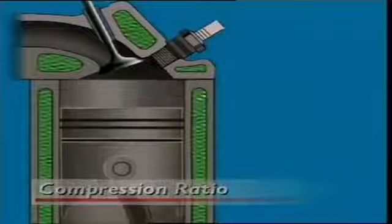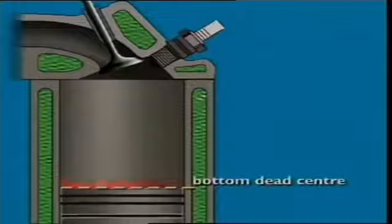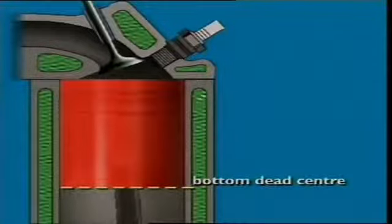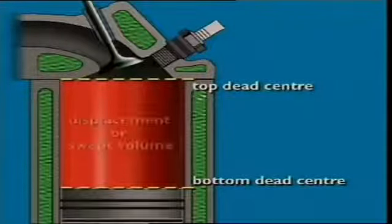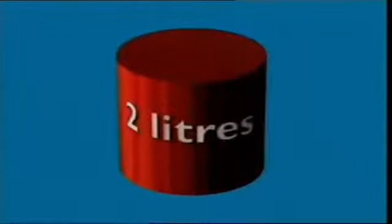Displacement is the volume a piston displaces in the cylinder as it moves from its lowest point, or bottom dead center, to its highest point, top dead center. This is also called swept volume. Notice that displacement does not include the volume above top dead center. Engine size is then the sum of the displacements of all the cylinders of the engine. It is called total engine displacement. For this engine it is 2 litres.